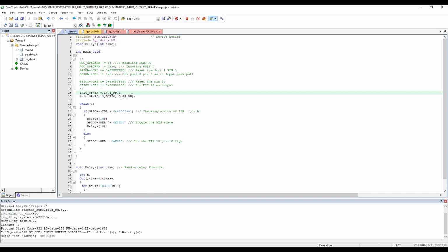We saved all this code in 2 lines, and we can set up all the other pins much more easily. So now what we have to work on is the direction and the setup of the pin, so how to read if it's a 1 or a 0 for a certain pin. So that's a good time to start creating the input function and to read the pin directly.